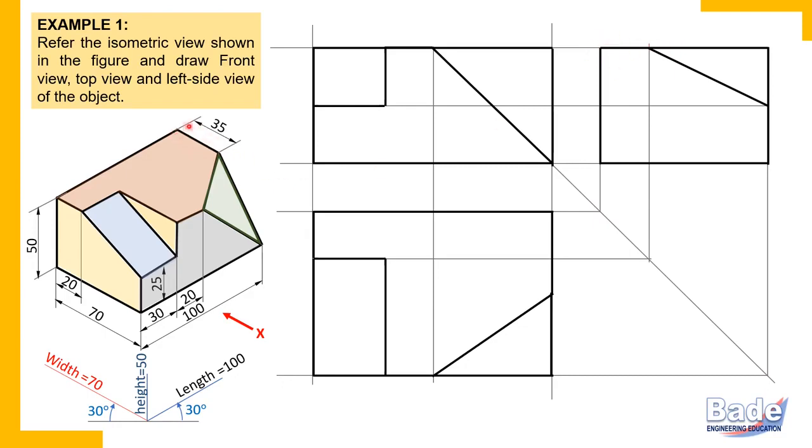Many students get confused how to measure this, where exactly to measure 35 in the side view. So simple. Check here from the back end. This is back side. At top, parallel to width. Width is in this orientation. So measure 35. Or you may project the 35 millimeter which we have already measured here by drawing projectors. So this corner is present here.